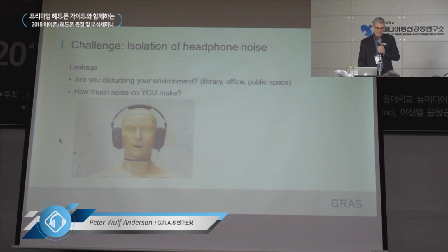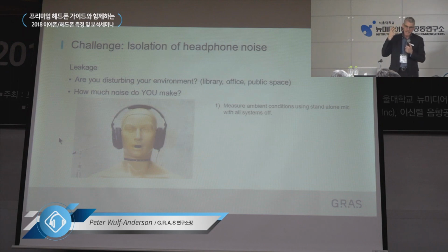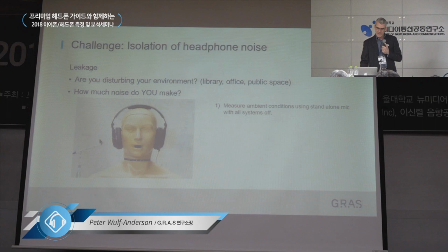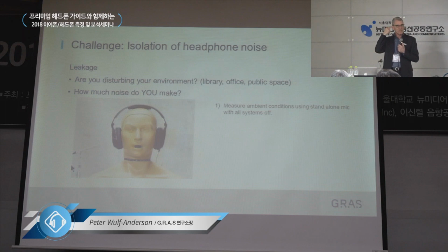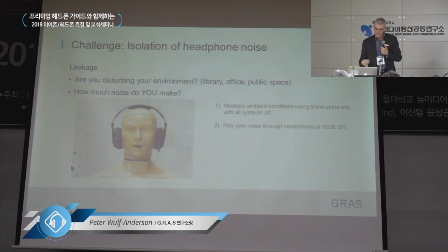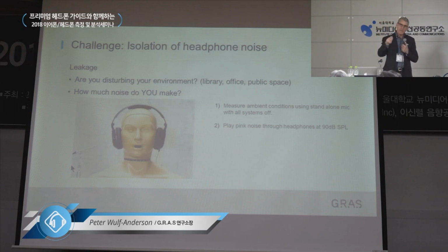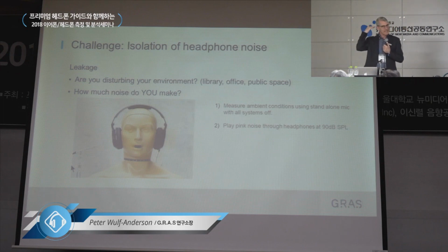It's quite easy to measure because you can just do a measurement with a microphone and measure the ambient noise pressure without any music in the headphones. And then you can do a similar measurement with pink noise played in the headphones at a fairly normal, loud listening level.